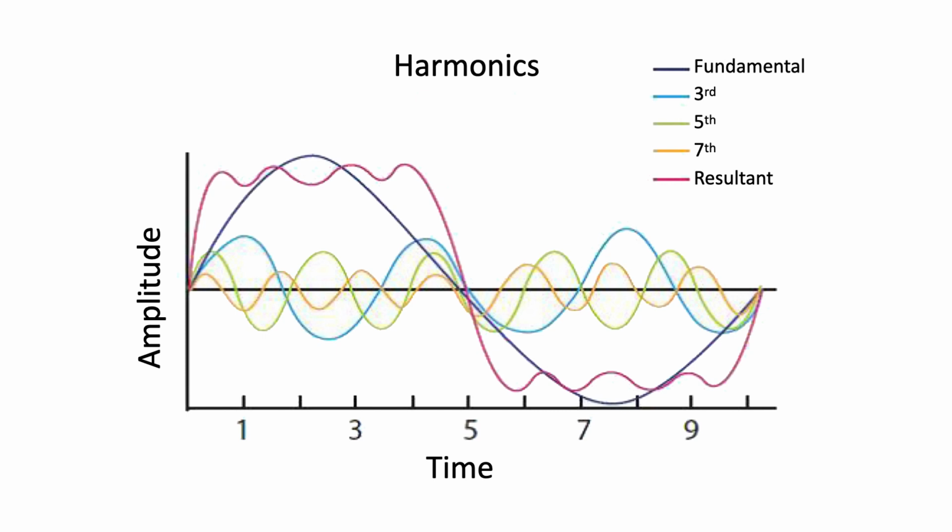All waveforms, no matter how complex, as long as they are repetitive, can be broken down into the sum of the fundamental sinusoidal wave plus multiples or harmonics of the fundamental frequency. In order to analyze this, we have a system of doing that called Fourier analysis. However, just an understanding that complex waveforms, if repetitive, are made up of the fundamental frequency plus integral harmonics or multiples of the fundamental component is what matters.